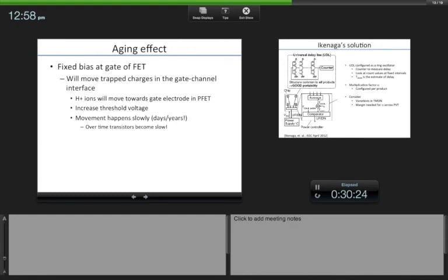Especially if a path consists of gates whose voltages keep the transistors always on, those become slower and slower. Certain circuit techniques have been developed to avoid keeping things on for prolonged periods of time, but regardless, things become slower. So after 5 years, or 10 years, whatever the expected lifetime is, if it's a cell phone, perhaps 2 years, the way people change cell phones, you have to ensure that you give a margin for aging also.